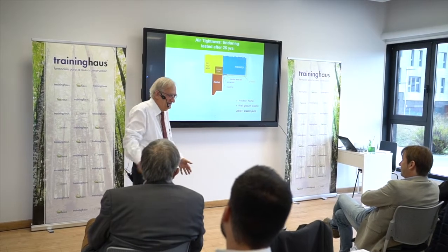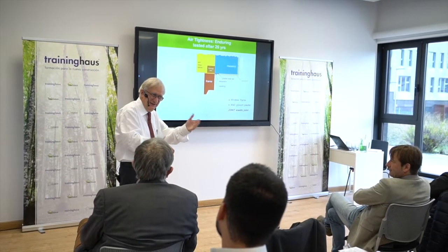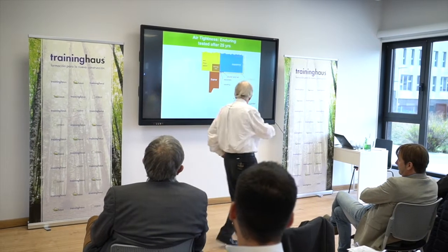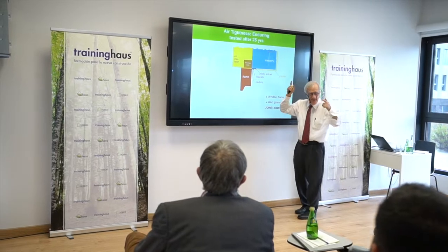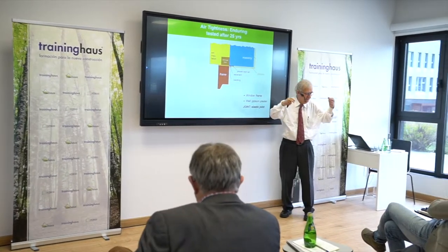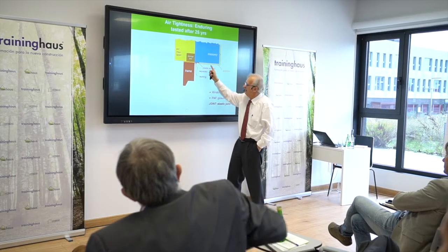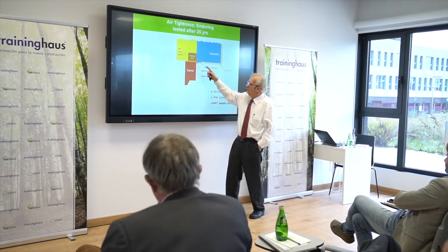So it doesn't make any sense to connect something which is not airtight in an airtight way to the window. What is airtight in a masonry wall is the plaster, the internal plaster. So this is a way of thinking here. As soon as you have realized this, it's easy to solve. What we have to connect is the airtight layer of the plaster with the frame. And that's the way you can do it.